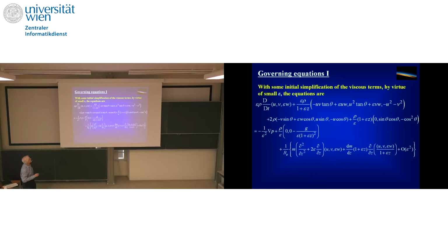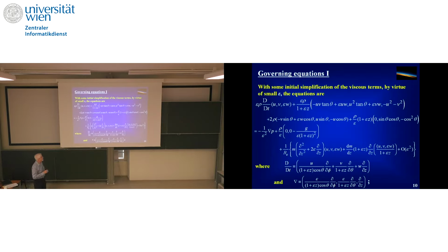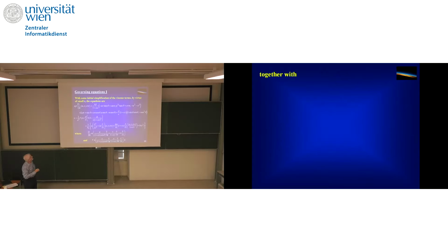Down here, those are the three components of our Navier-Stokes equation, which I will write out individually in a moment or two. The d by dt is the normal operator, except, of course, although it's the material derivative operator, because of the choice we've already made, there's no partial d by dt in here, so I've suppressed it. Right, I think that's straightforward enough.